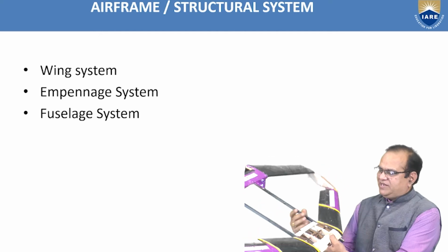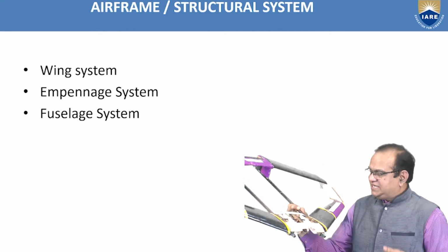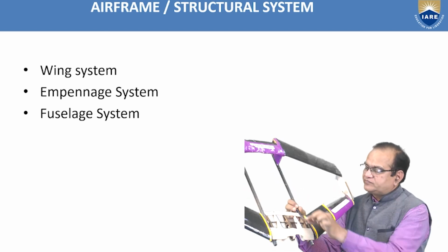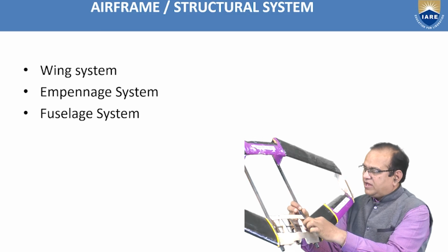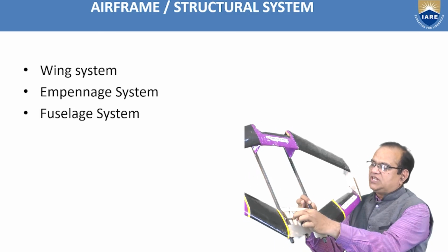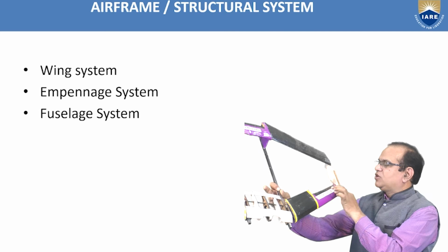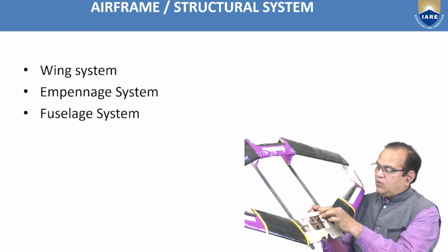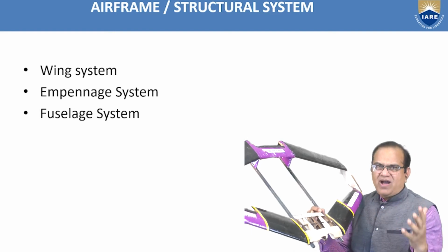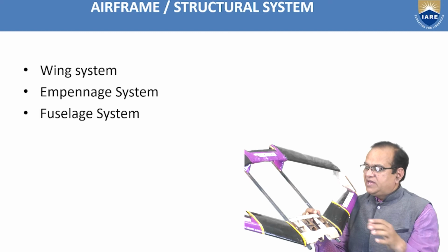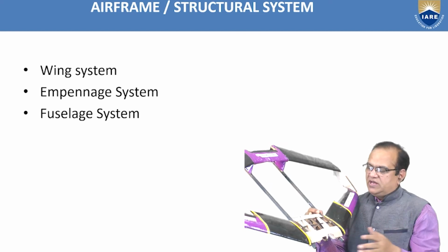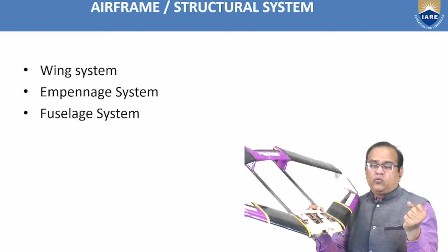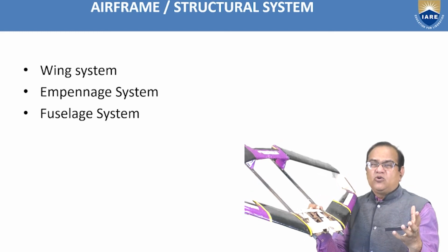Okay, this is made by our students, and you can see here, these are the wings. Here also if you see, the wings are made of airfoils. These are airfoils 1, 2, 3, 4, and here also everywhere you have the airfoils. These airfoils are made of wood, and as per the requirement of the aircraft lift, different airfoils are used. And here we have the longerons. These longerons are the main component taking the total load of the wing.